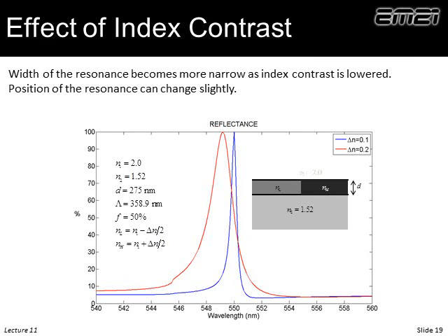So our grating, there's a number of ways we can produce that. We can produce it as bumps. We can actually build in regions with low and high refractive indices. And depending on the strength of that grating, or the contrast of the refractive indices producing the grating, that will have an effect on the response of the filter.